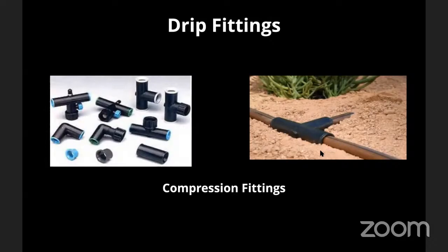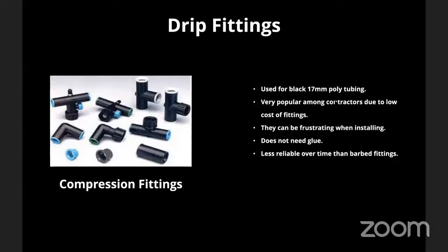However, the barbed fittings are going to be more resilient. And so if you're trying to figure out whether this is an option for you, that's another reason why it's best to go to a local irrigation specialty supply store: the people behind the counter can help you make sure you're grabbing the right things. You have a much better chance of leaving with all the right parts than if you're just in the aisle at the big box hardware store scratching your head. Some people like compression fittings because they are very inexpensive and take a little bit less elbow grease, a little bit less muscle to push together.